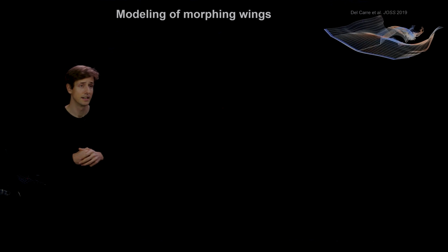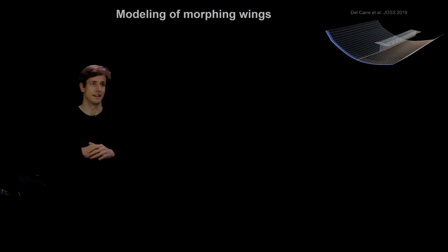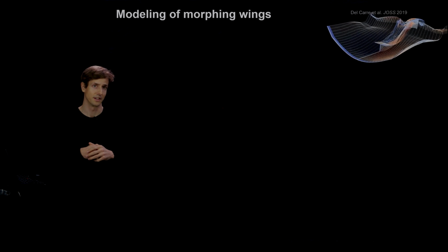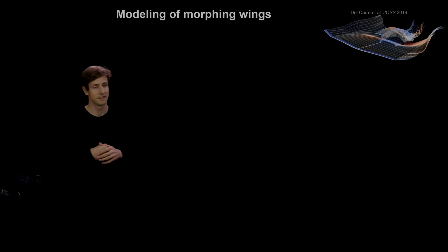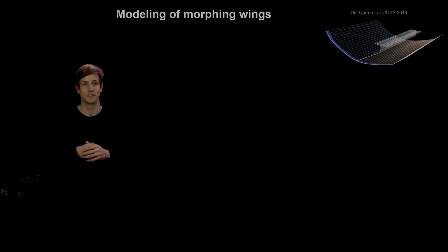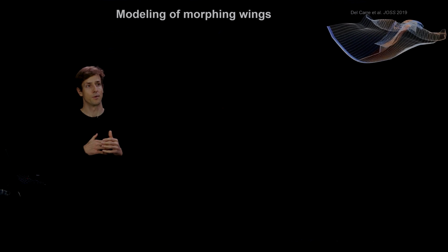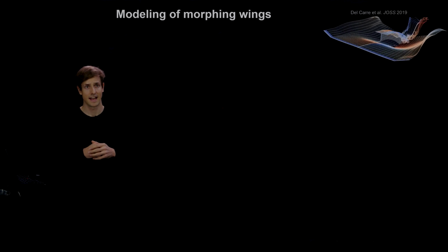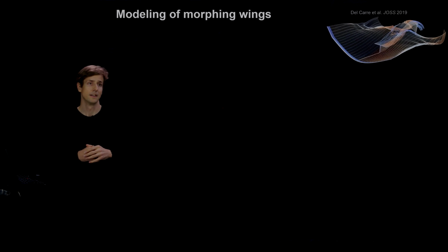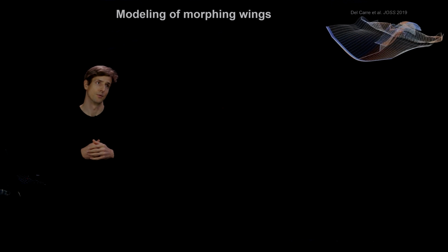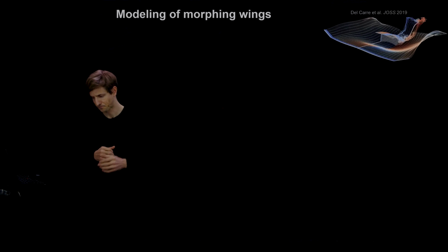And what you can see here in this animation is a T-tail high-altitude, long-endurance vehicle that is encountering a gust. And they simulate this very flexible aircraft using their simulation toolbox, SHARPy, where they model the wing structure as exact beam elements and couple this structural model with an unsteady vortex lattice method.